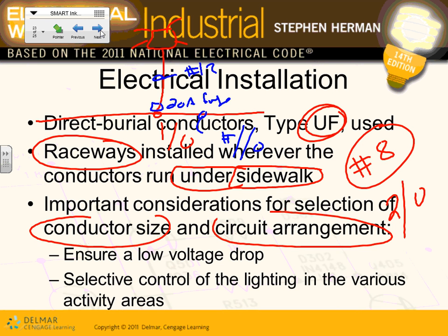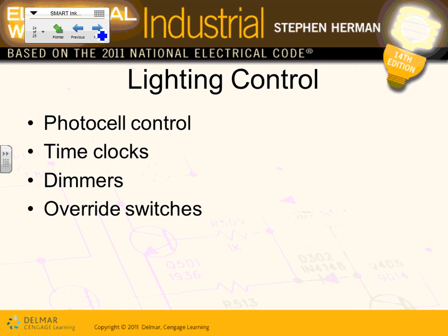So what's the issue? Voltage drop is a major consideration. Selection of control of the lighting: we talked about two types of control, either timers or magnetic contactors, which is some form of a timer, controlled by a clock, astronomical clock, or a timer. And then you can interface it with your security system, your heating and cooling system, building automation system. All of these are completely interfaced. Any comments, any questions, my friends? Joe? No? Okay, so that's basically it.